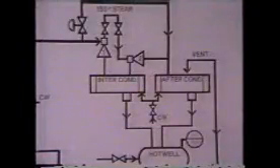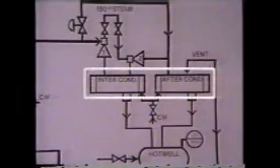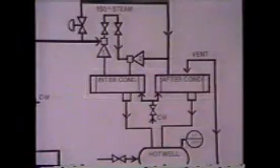For example, if the vacuum jets are shut down improperly, water from the vacuum condensers could be drawn back into the column when the column is restarted. This could contaminate the distillation products. Well, let's take a look at the short-term shutdown procedure.